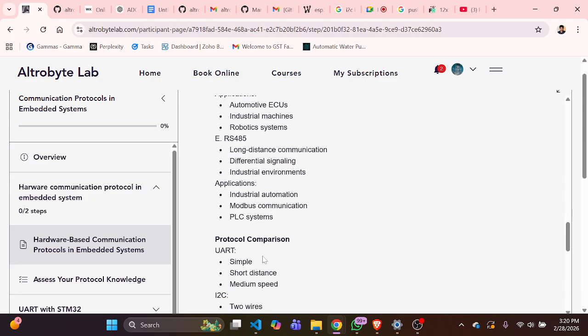Then our next protocol is RS485, a long distance communication protocol. When we want to implement communication inside plants or warehouses through a wire, not wireless, it is dedicated to long distance communication over a wide area. There could be some limit, but mostly for long distance communication over wire, we choose RS485.